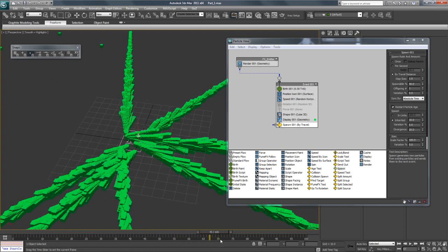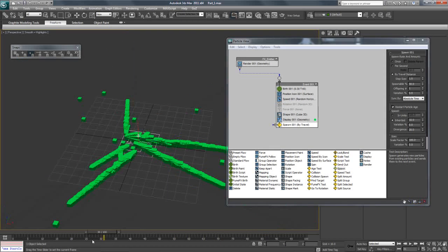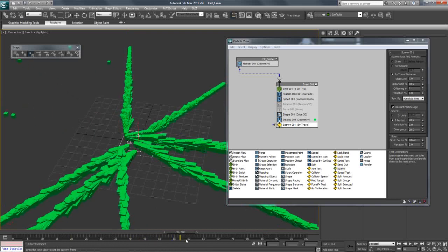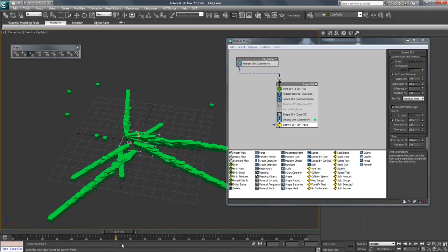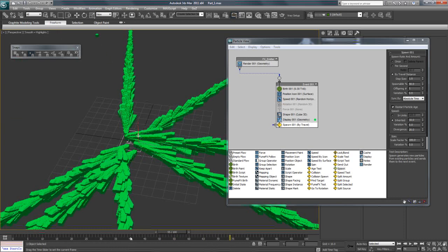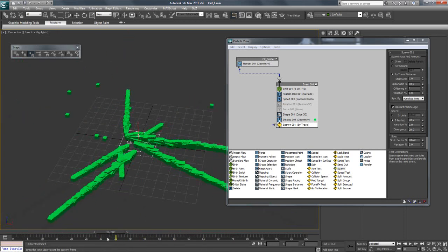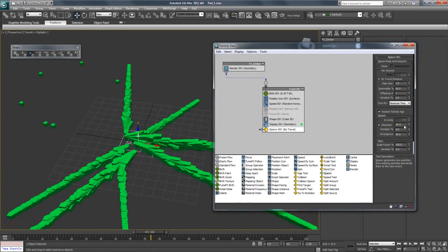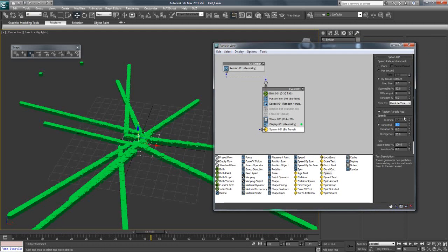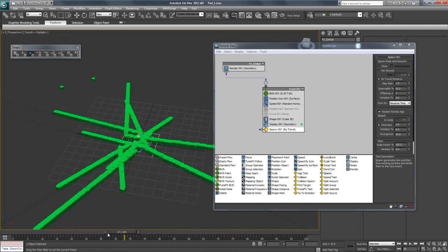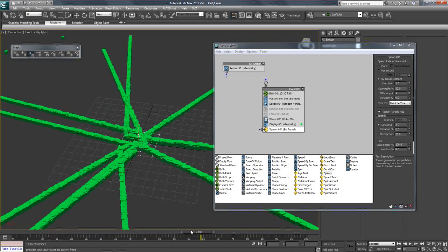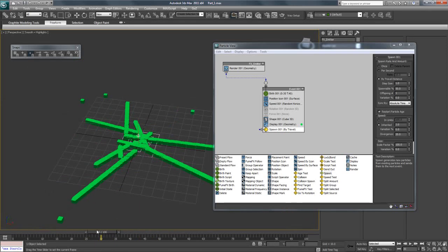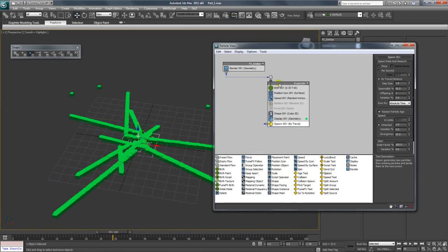So you can see what happens is we have these particles shooting out almost in a straight line, and this is what we're going to do to have these things follow basically this linear path. Even looking at this, you can probably come up with a lot of ideas. Like this looks like some sort of vegetation that's growing, if you look at the endpoints. When you play around with particles, you tend to find out these different ways to do things. So I'm going to change the inherit from 10 to 2.0, and basically this is bringing the particles closer together, to get a sort of straight line going on here.